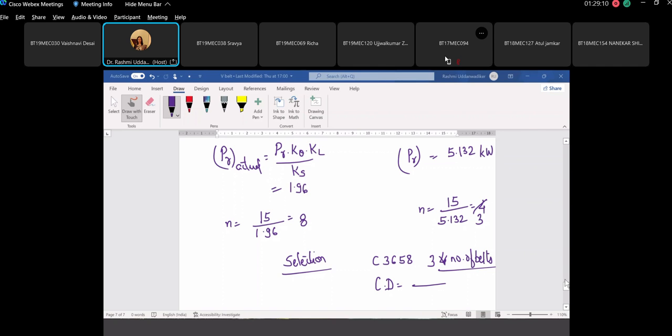Vinayak, Sahil? Ma'am, why does bending load decrease with increase in center distance? It will bend less frequently, right? If the center distance is large, when the belt is going from this end to the other end, it is getting sufficient distance to relax, and again it has to bend. Again, it is getting a lot of distance and time to relax, but with a lesser center distance, it bends more frequently. For the same RPM of the belt, it has to bend many times. Can you visualize this belt rotating between the two pulleys, bending more frequently? Yes, ma'am, got it. Okay, good.